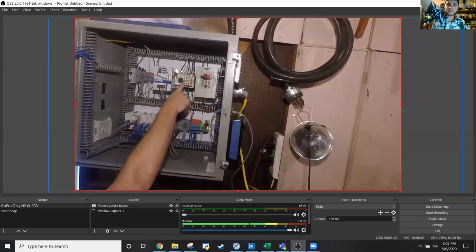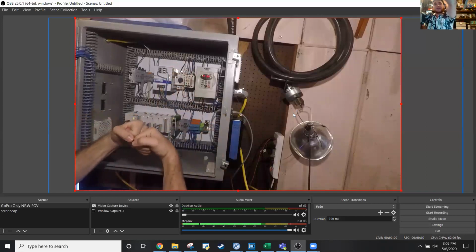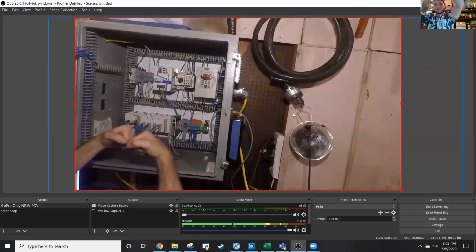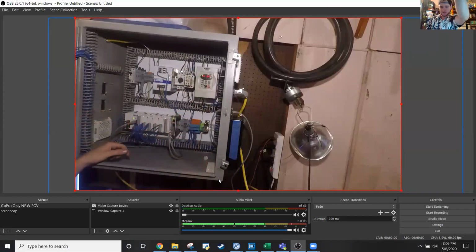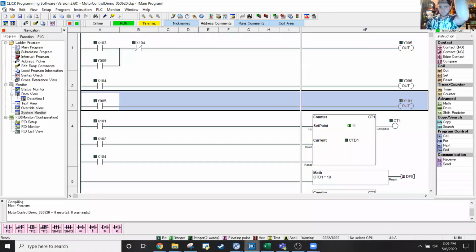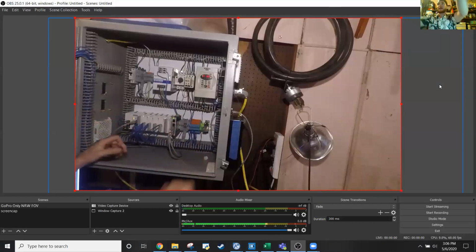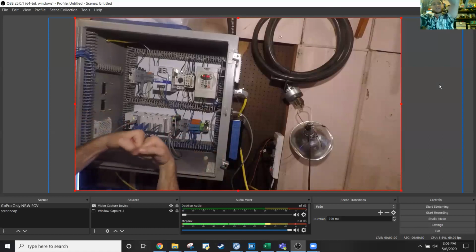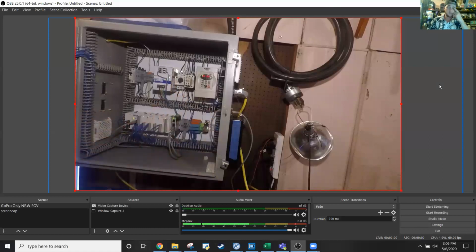And basically all this contactor is, is two big metal plates that chunk together, right? And then it's spring loaded. So if you don't have an input signal to it, they're separated and there's a physical gap. That motor contactor is wired to Y101. And so when Y101 is fired, it sends the signal that makes that contactor chunk together and lets that electrical signal travel out to the motor.